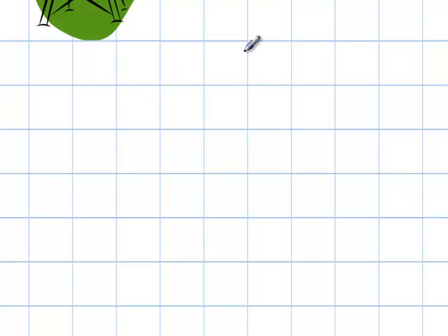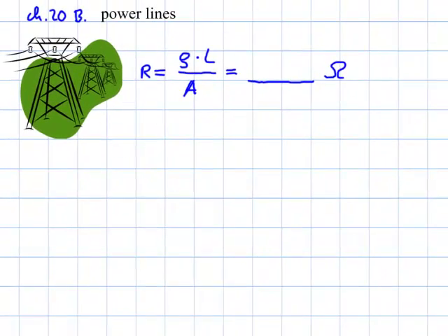So that's just a matter of plugging in numbers. Use the equation that connects resistance with resistivity. The area is given in square meters in the problem. The length is 10 kilometers, respectively 10,000 meters. And the resistivity, you look up in the chapter, it lists it for aluminum as 2.82 times 10 to the negative 8 ohm meters. Units, the meters or meter squared will divide out, and you're just going to be left with ohms.